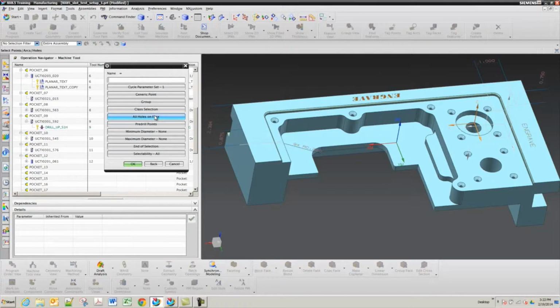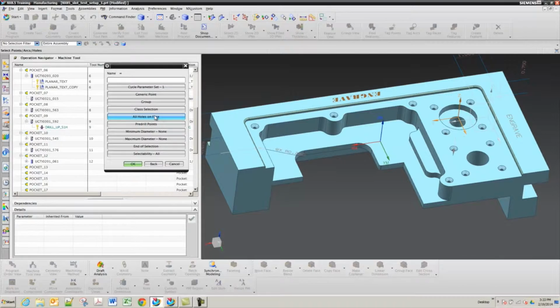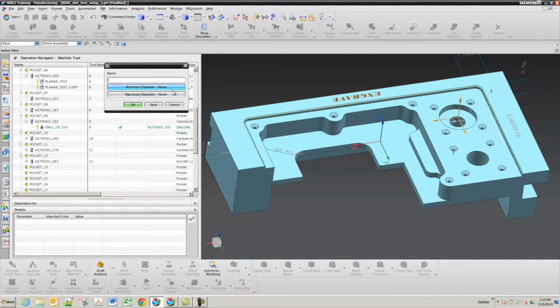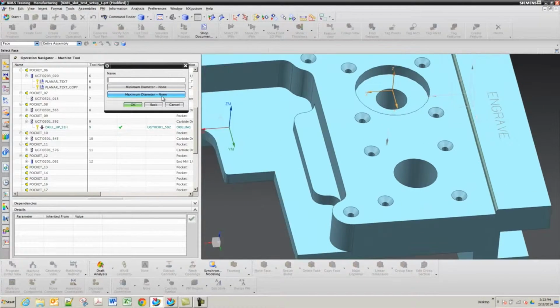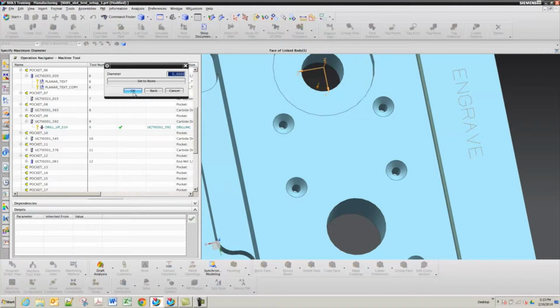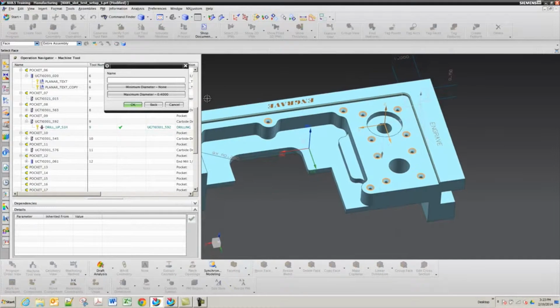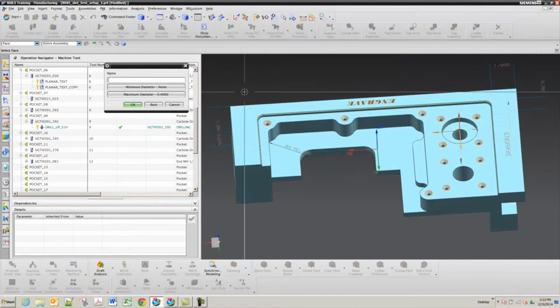And then down on here there's all holes on face, but I could filter by size after I do that. So it's saying minimum diameter, maximum diameter. For maximum, if that was an eighth, I'd guess 375 should get it, wouldn't you think? Or maybe 400 thou, so 0.4. And then I just pick the face. Yep, that worked. And it picked all those holes.